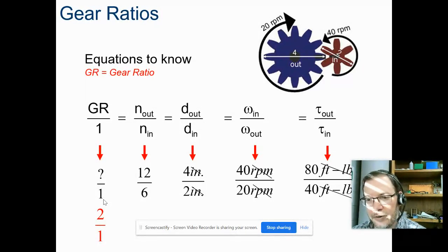They can drive them around. They are a really good example of a situation where something like this is happening, where I have a very large gear ratio because the motors that drive those are very, very small. They have very small motors. They have high RPM, very low torque. So they have very little power, but they spin really fast.